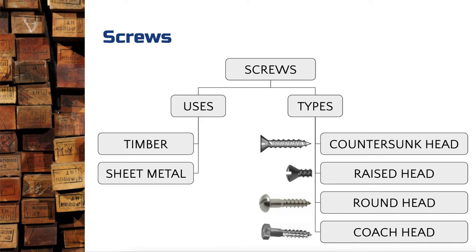There is the countersunk head screw. It's the most common screw that we use in the workshop and probably the one you're most familiar with. It's indicated there, that top image. You can see it's sort of got that dovetail flare out head type and it's got a very flat edge. So I'm just going to turn on my annotation laser pointer tool. You'll see it's got that very flat edge. That flat edge is designed to be aligned with the surface of the timber that you're screwing into or below it. So it shouldn't be sitting higher than. So it should be equal to or below the surface.